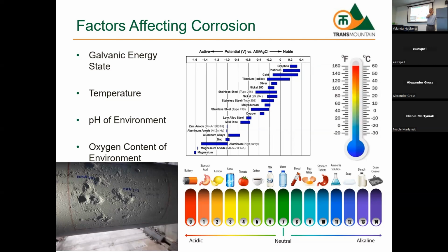But it depends on the environment, right? Because in some environments it would be the other way around, depending on the pH of the environment. But this is like a neutral salt. In neutral, yes, that's correct. Anytime we talk about corrosion, corrosion is defined as the degradation of a material in its environment. So if the environment, which is the electrolyte, has a different pH, that's going to determine the corrosion rate of the metal. So you're correct.